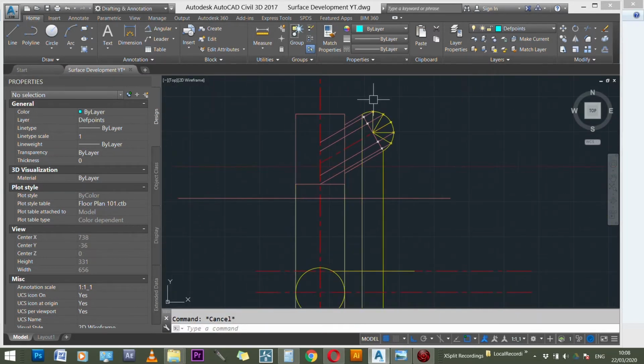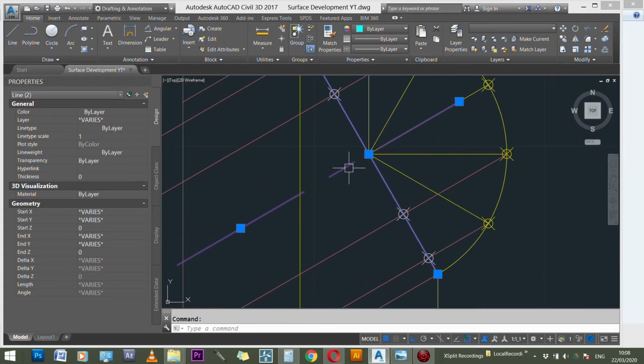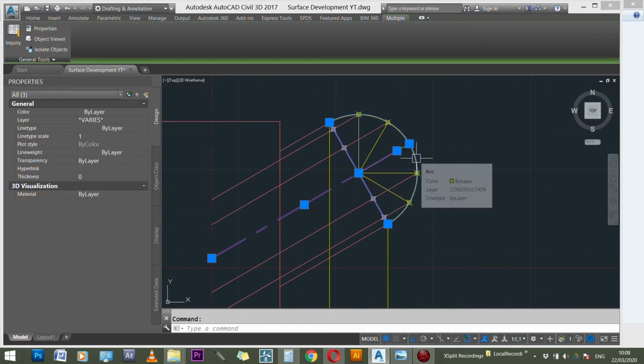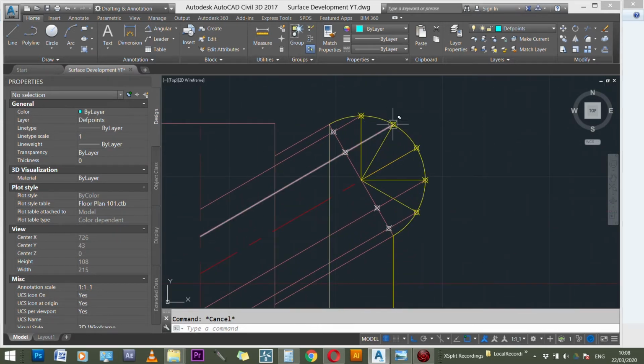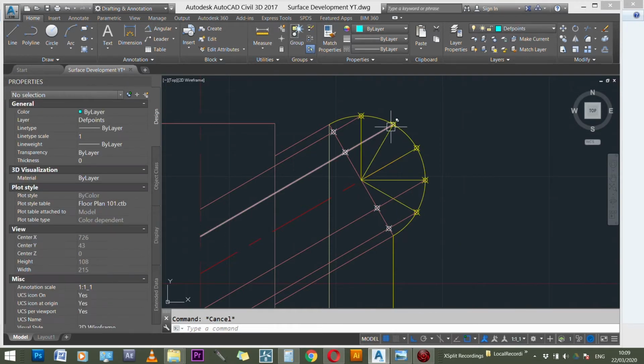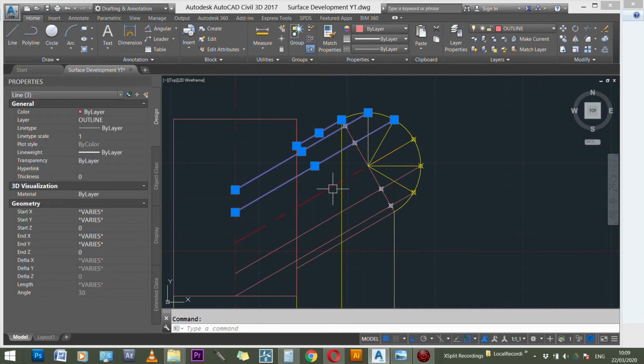So far, just to recap, we have divided our slanted cylinder into 6 pieces by placing a semicircle on our center line at the top of the cylinder, where the center line of the cylinder intersects the end of the cylinder. We have cast a semicircle, which is here, and then divided the semicircle into 6 pieces. Each division on the semicircle comes all the way back to the center of the semicircle. We have done that, brought each division to the center like what we have here, and then we created parallel lines from this edge at each division. So these are the parallel lines that were created.